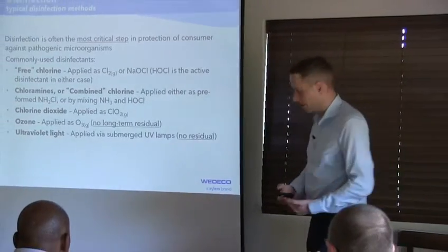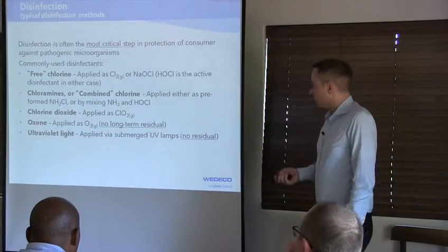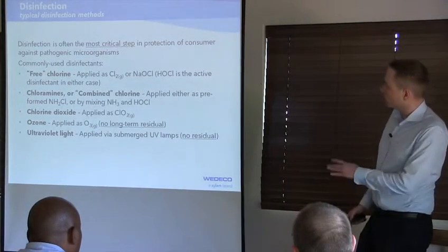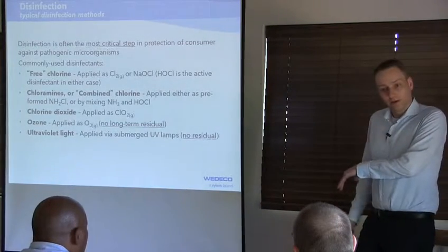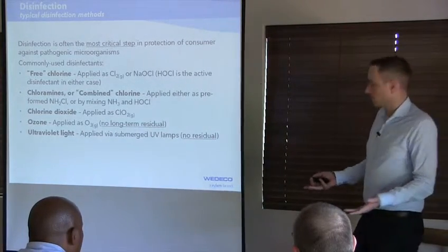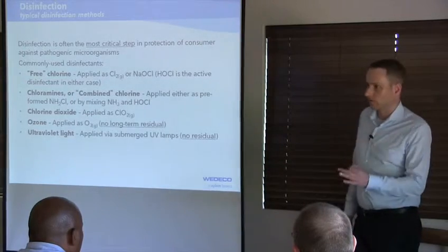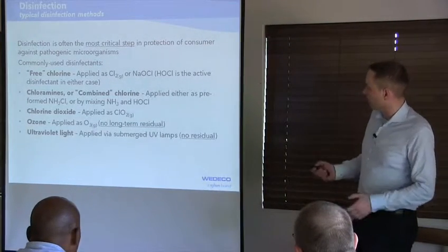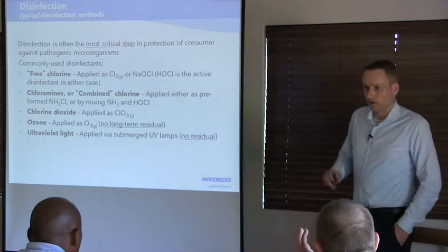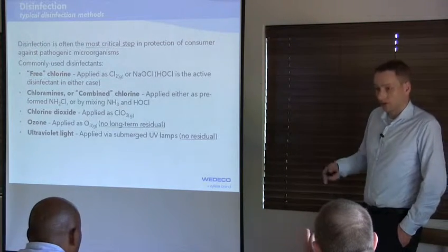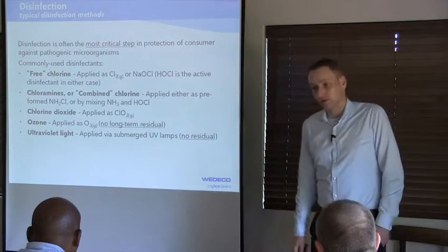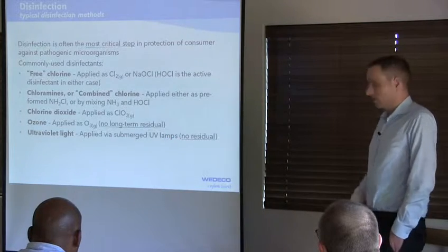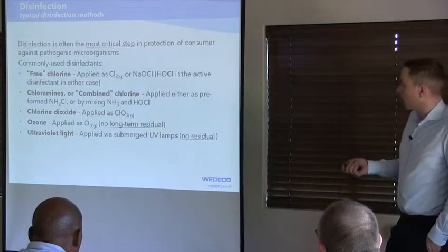UV light disinfection and ozone disinfection. As we offer both solutions, I would not say ozone is not as good as UV for disinfection, but if you compare both technologies, ozone is, for a typical disinfection purpose, not cost efficient compared to UV. Typically ozone systems are normally 3 to 4 times higher in operating costs because of the high power consumption. It also, like UV light, doesn't provide a long-term residual.